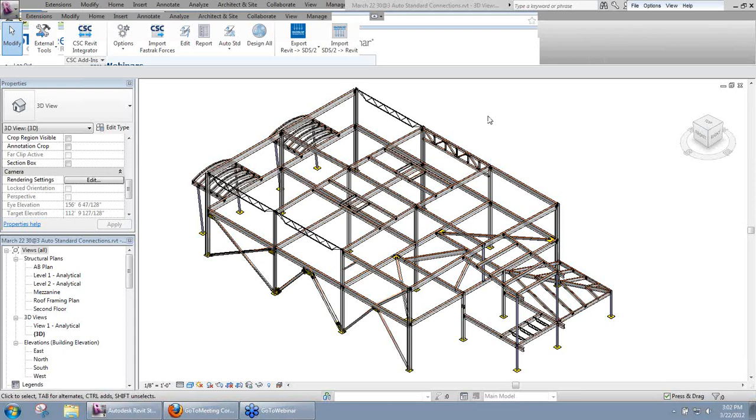So basically an auto standard connection is what we want to try and use the most on our projects. The reason being is that these auto standard connections are set up, most typically, right away at the beginning of the project before we start modeling. Then, based on our different framing situations and what material types we have framing together, we allow SDS2 Connect to determine whether it designs an end plate, clip angle, or shear tab based on what you have set up for that.